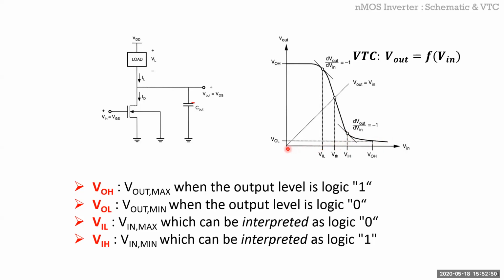So you have this definition for your input low, this definition as input high, and obviously this is the region you don't want to be in, and that's the region we'll define more. And then the other term we use in digital logic, CMOS logic, is this point, which is called VTH. And please don't confuse this VTH. It's an unfortunate choice of terminology, but this is also called VTH, but this is not your threshold voltage. This is the voltage at which your Vin is equal to Vout.